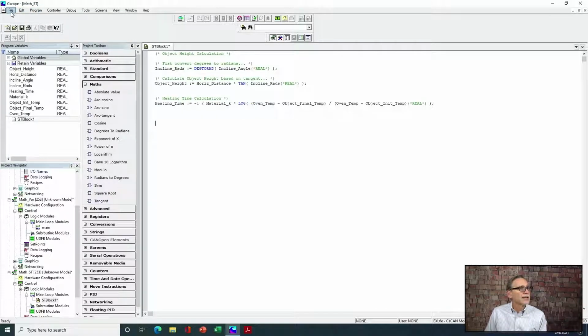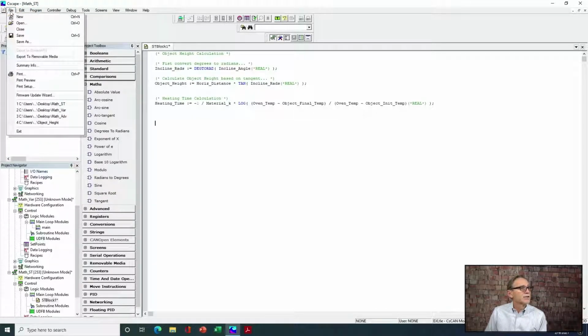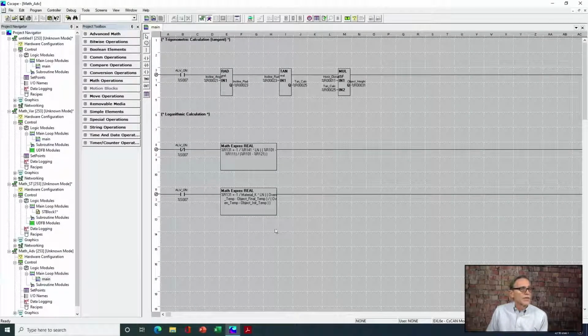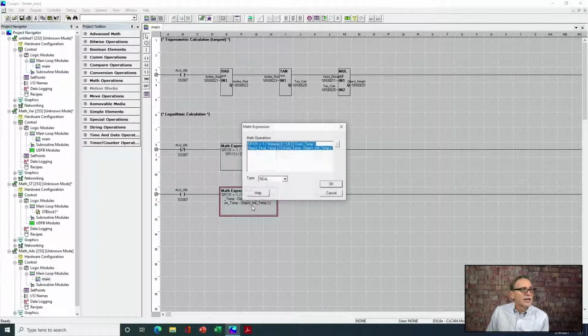Let's go ahead and take a look, all the way back, let's say, to advanced ladder and see how we would do that. Okay, so here's our logarithmic calculation. All right, we were able to write the whole thing out with the exception of the result. Again, a limitation of advanced ladder, register-based, is that with the result, you have to put the memory location as opposed to the variable name. I think that's probably something that we could enhance, but that's currently the way it works today.